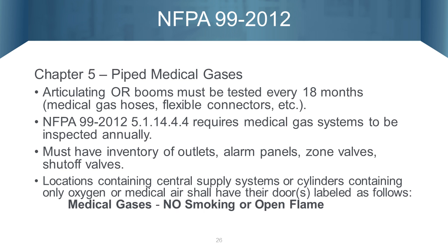Also, we're requiring medical gas systems to be tested annually. Most organizations do that, and even though it was not required previously, now it's actually a requirement. We must also have an inventory of all of our outlets, alarm panels, zone valves, and shutoff valves.